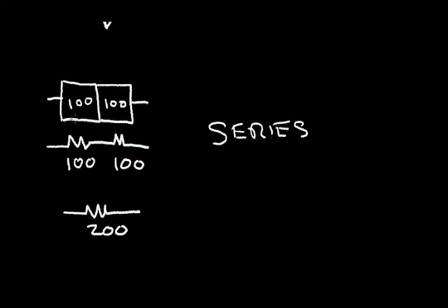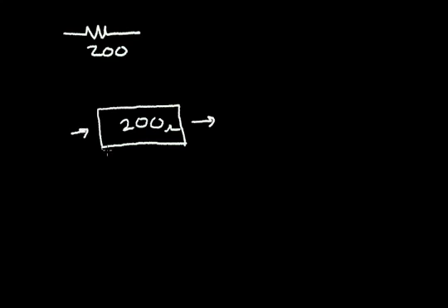So now I'm going to take the same resistor shape, these 2 squares of resistance, and I'm going to put that down here. So we know, since this is 2 squares, that this is equal to 200 ohms, and again the current is flowing in this direction. Now let's take the same material and double this dimension. We'll add another 200 ohm resistor here. And again, the current is flowing in this direction.